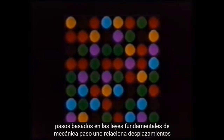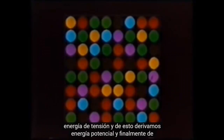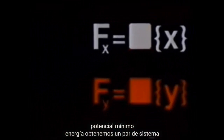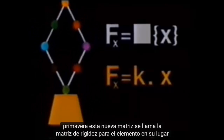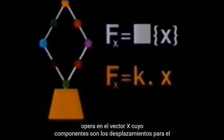This matrix is now the starting point for a series of steps based on the fundamental laws of mechanics. Step 1 relates displacements to stresses. From stresses, we obtain strain energy. And from this, we derive potential energy. And finally, from minimum potential energy, we obtain a pair of system equations for the complete element. By analogy with the equation of a simple spring, this new matrix is called the stiffness matrix for the element. Instead of a single displacement x, the matrix operates on the vector x, whose components are the displacements for the whole element.